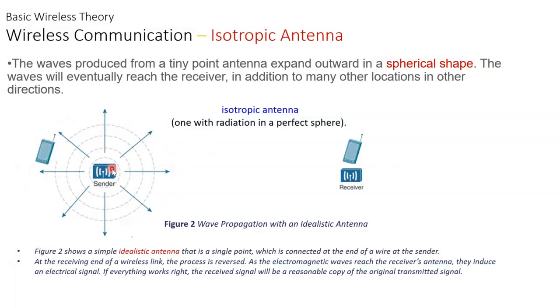When I mention that any antenna has a gain of 10 dBi, it means it has a gain equal to 10 dB compared to the isotropic antenna. This is a reference. This is a theoretical antenna. This is not a physical antenna. This is the reference. Okay? So it is used as a reference for comparing real antenna gains measured in dBi, which equals gain relative to isotropic antenna. So it does not exist physically, but it helps engineers benchmark how directive or efficient a real antenna is. This is the isotropic.